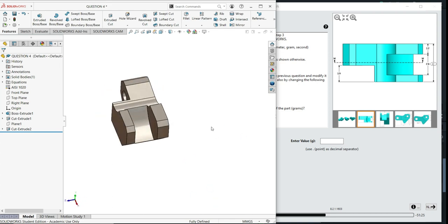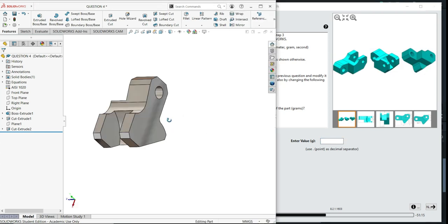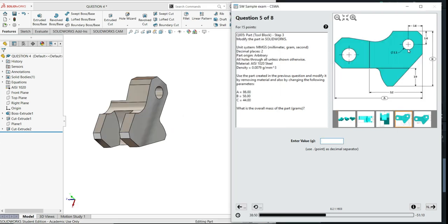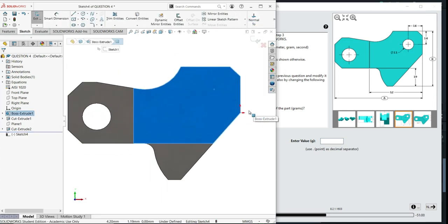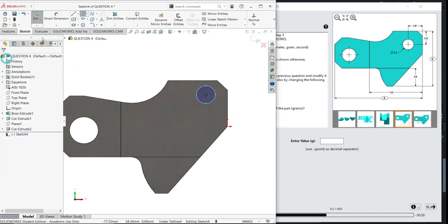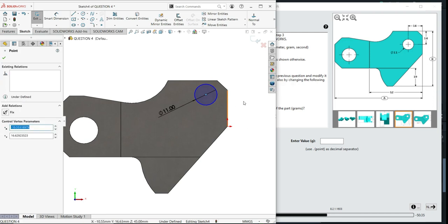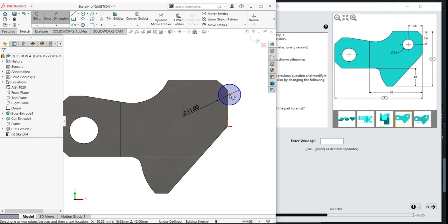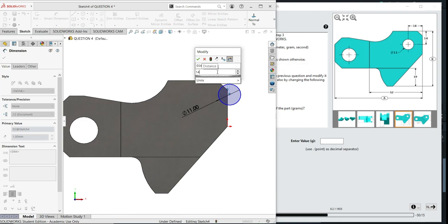As you can see here, we're going to make the next part, which is that hole. This hole here has a diameter of 11. Just come here, sketch, and then flip to normal. Here you make the hole like there. Size would be 11. Then you simply make the dimension. That point will be 14, according to the drawing. Just make sure to make here 14.